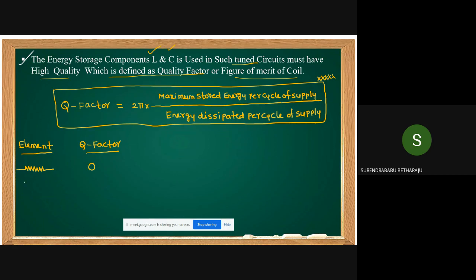If it is a pure inductor, practically not possible. Talking about a pure inductor, what is the quality factor? The resistance is 0. Resistance is 0 means energy dissipation is 0. Energy dissipation is 0 means the quality factor is infinity. If it is a pure capacitor, what is the quality factor, students? Infinity. These observations are important from a competitive point of view. That's why I'm giving this.